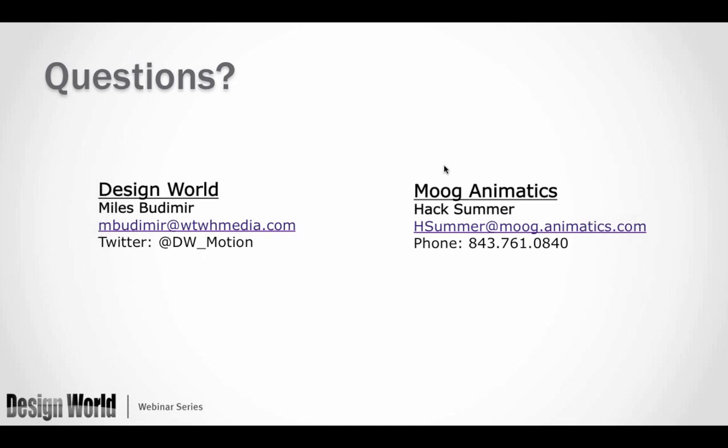With regards to vacuum, I mentioned pressure. If you get all the way down to vacuum, you cannot dissipate heat in a vacuum. We do not have vacuum rated products. But what I will say is, with regards to the pressure, vacuum, sealing, and whatever, it is the standard product put in a much better housing, so you get all the benefits of the SmartMotor that we've always had, which include position mode, velocity mode, electronic gearing, electronic camming, and fully programmable. So the biggest advantage is you've got all that control capability within that environment, whatever that environment may be.